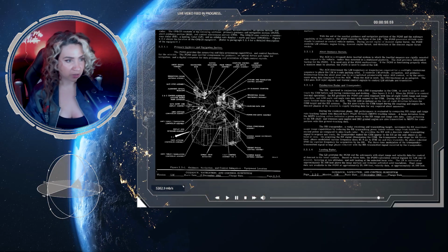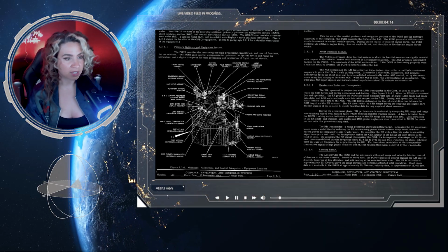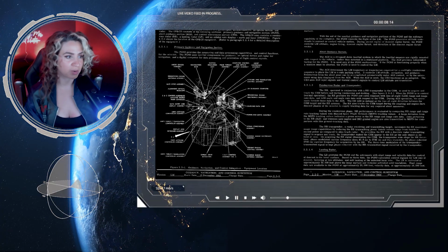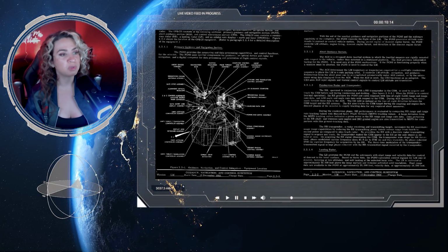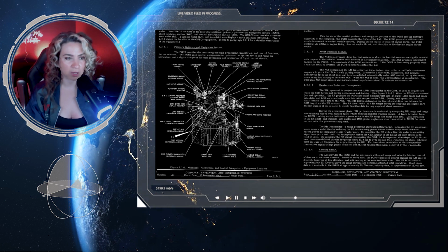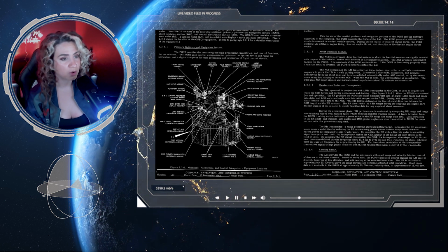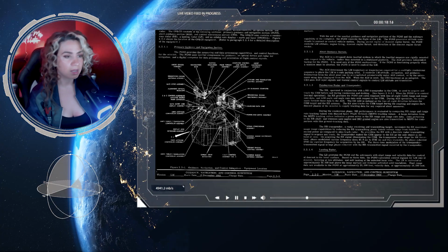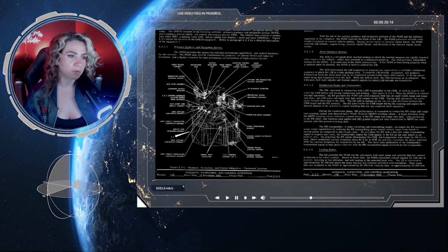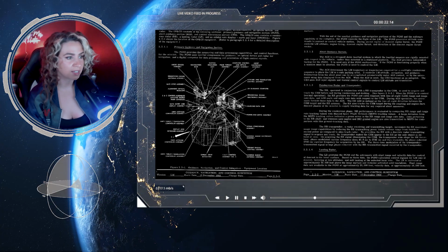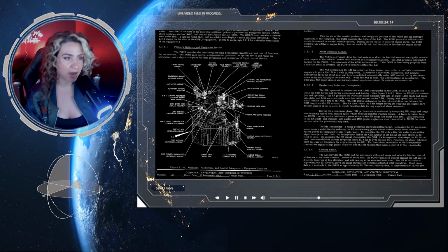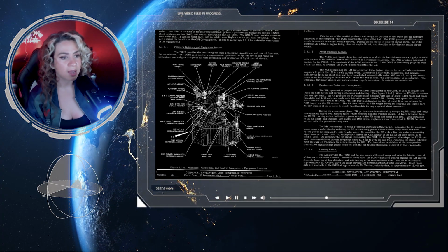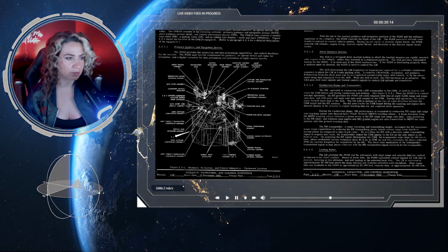The RR transponder, a radar receiving and transmitting target, increases the RR maximum usage range capabilities by reducing the RR transmitting power losses versus range from fourth to second power as compared to skin track radar. By providing the RR with a discrete radar transmitting signal to acquire and track, the transponder makes the CSM appear to the RR as the only object in its field of view.